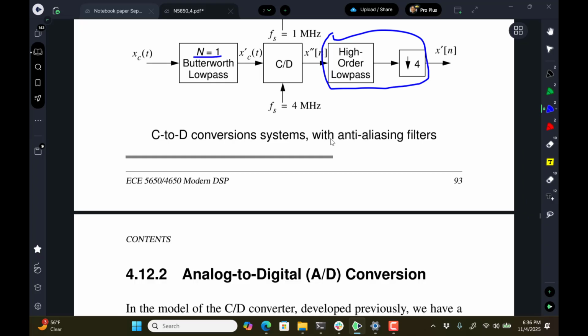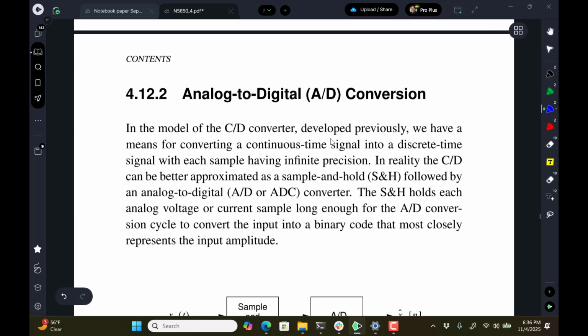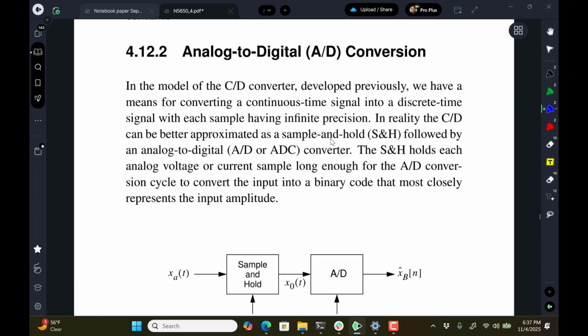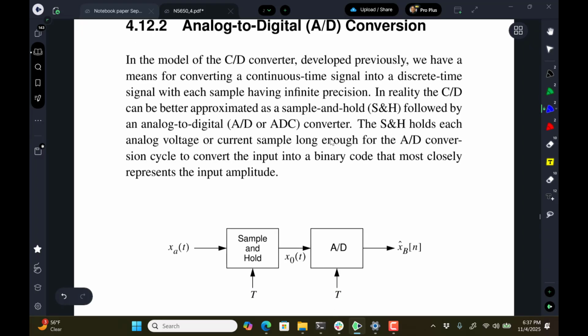So that's just a little discussion about anti-aliasing filters and some trade-offs that have to go on. Chances are multi-rate processing is good. So the next step is to head into the A to D converter, and the first thing is the sample and hold. The sample and hold is generally there. If it's a fast converter, it might be a separate circuit out front. If it's a lower rate converter, it might be built into the A to D, but in any case, it's something that can take the input and hold it long enough so that the converter can go through its conversion process while the signal is standing still.